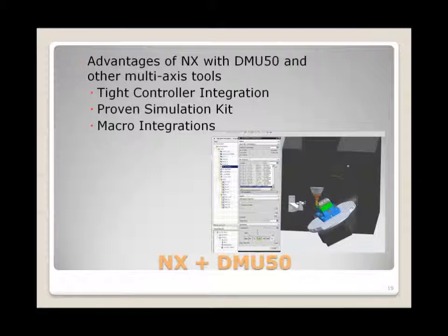And then having a tight controller integration across many different controls, as John stated, the Mitsubishi, Fanuc, Heidenhain, Siemens, and obviously many others, and being able to simulate that with a full machine simulation and looking at the actual code that will run on that machine.